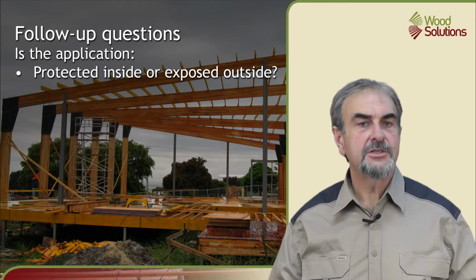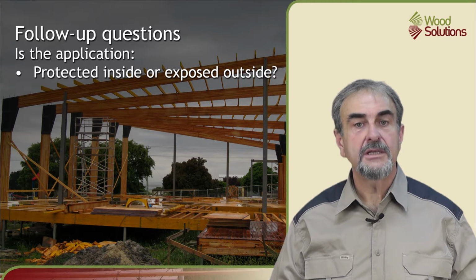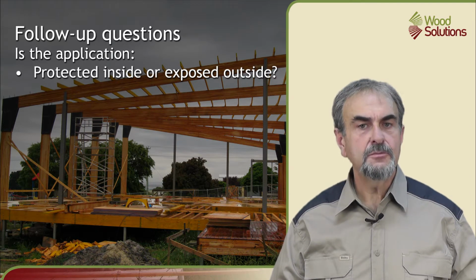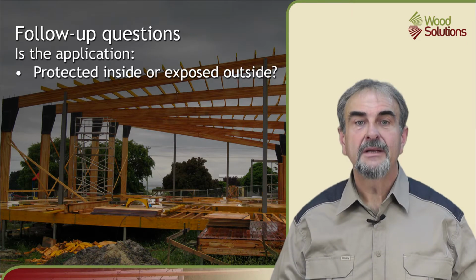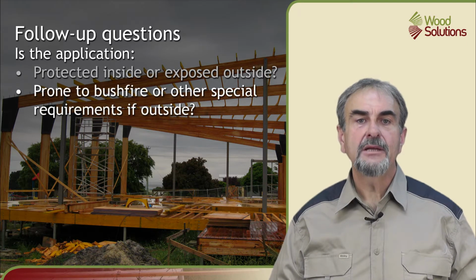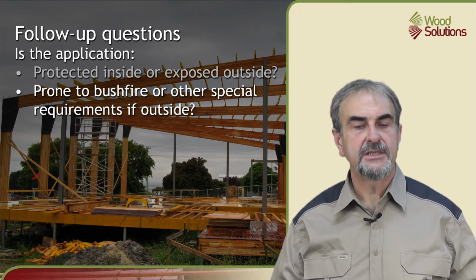There are follow-up questions to ask. The first is if the timber is to be used inside or outside. For structural material used inside, termite resistance or protection is often important. For structural material used outside, durability is a key consideration. The next is if material outside is prone to bushfire or other special requirements. These points are discussed in other presentations in detail.